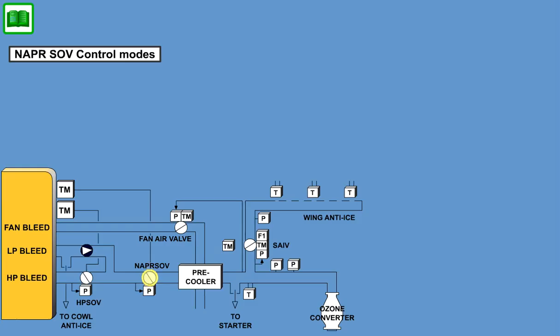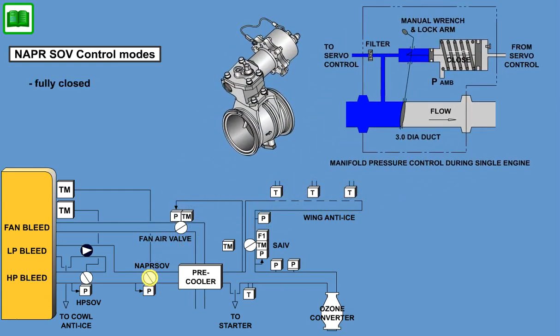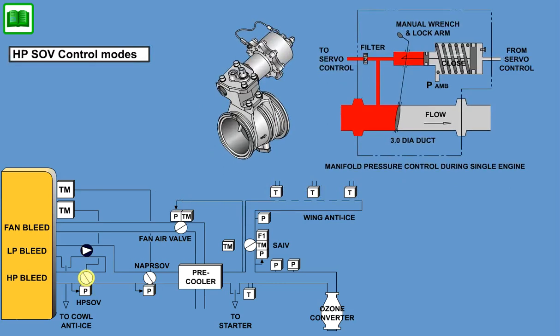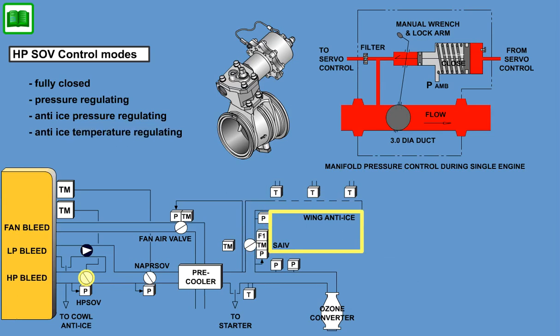The NAPR SOV control modes are fully closed, pressure regulating, anti-ice temperature regulating, anti-ice pressure regulating. The left or right HPSOV has the following control modes: fully closed, pressure regulating, anti-ice pressure regulating, anti-ice temperature regulating.